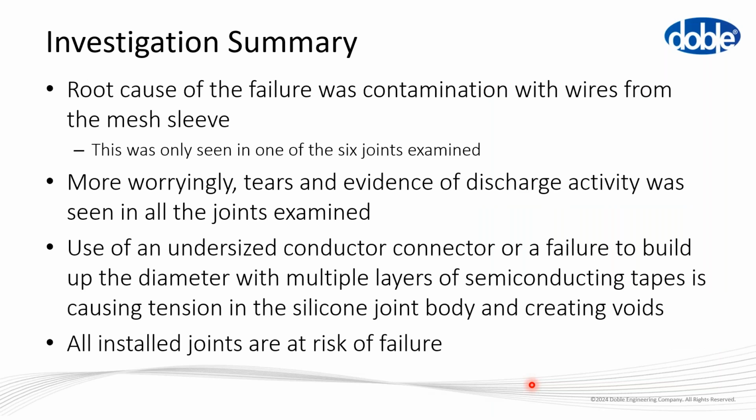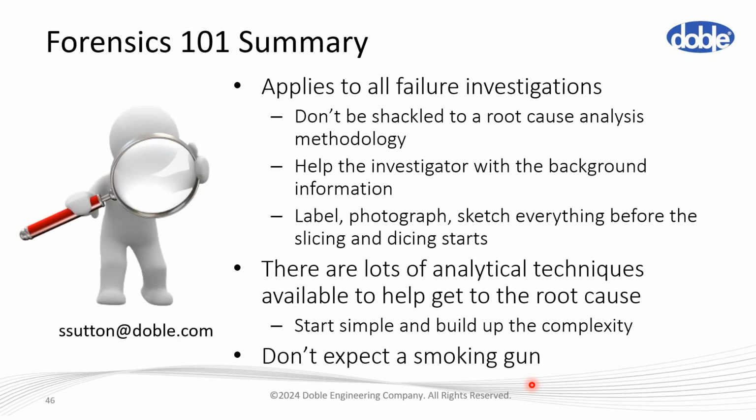So the failure in the cable we examined was down to the little wires getting into the tapes. But more worryingly, we found evidence of discharge and tearing in all the joints we looked at, which probably means if they used the same size conductor connector on the entire circuit, every single joint was probably at risk of having failures in the future. And there's not very much the customer can do other than excavate the cable and replace the joints at that point. So that's the end of the little case study.